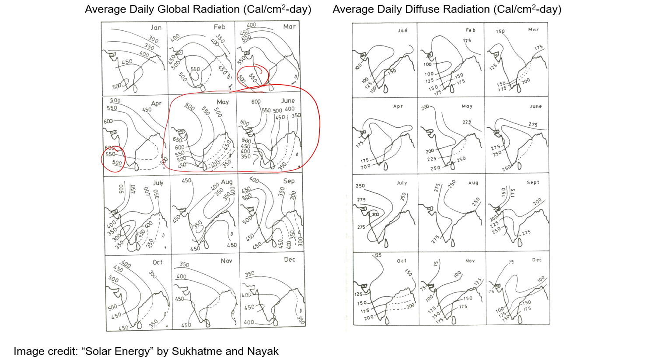So, these plots give you a good idea about at which location, at what time of the year the radiation will be maximum. You can see for northwestern India, the better months are May and June, whereas for some place like Kerala, January, February, March, April are better. January will be a very bad time for North India, because there is a lot of smog or fog because of winter, and there is a lot of moisture in the atmosphere.